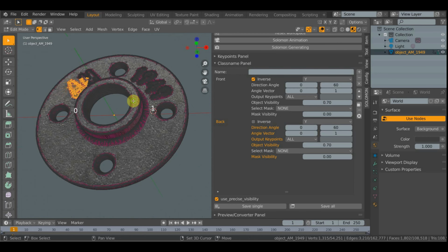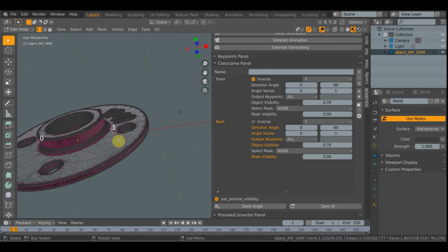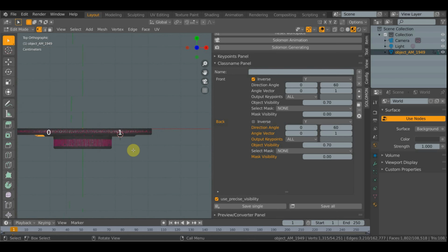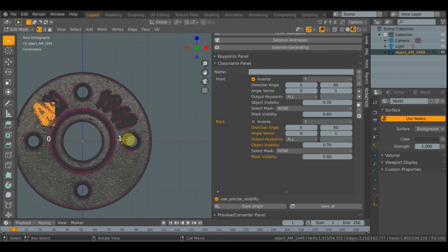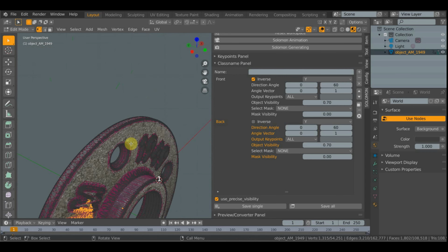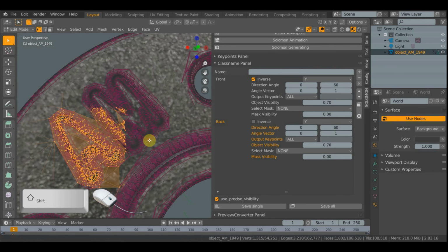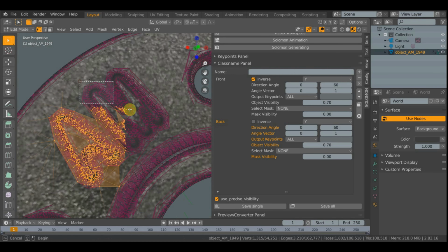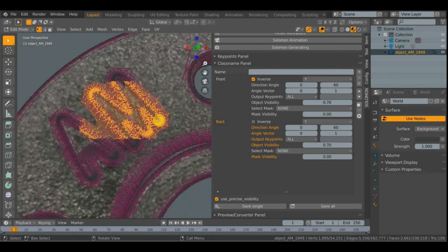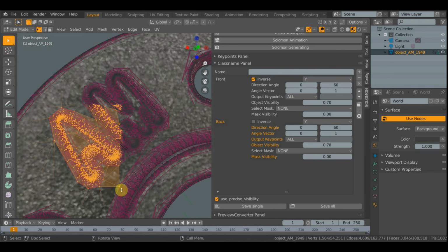It's very difficult to select the region of interest accurately at once. I suggest you select the majority of the region of interest the first time, and for the consecutive parts you can press Shift plus left click and draw a square. Then every time you draw a new square pressing Shift, the selected area will be added to the initial selection.